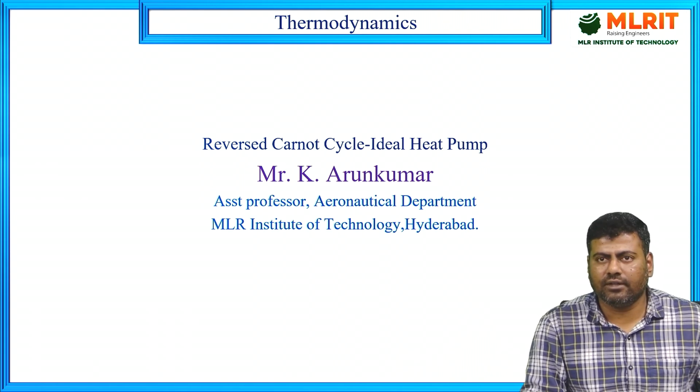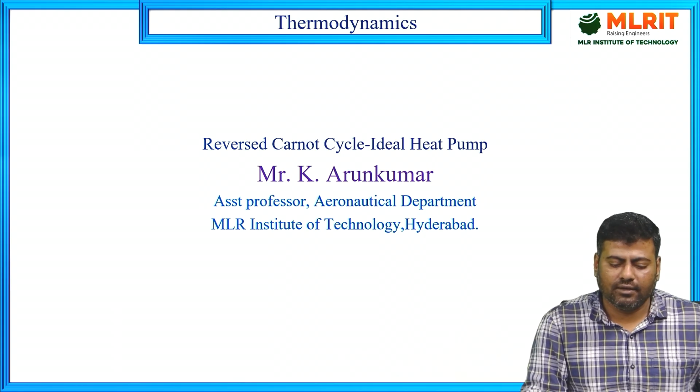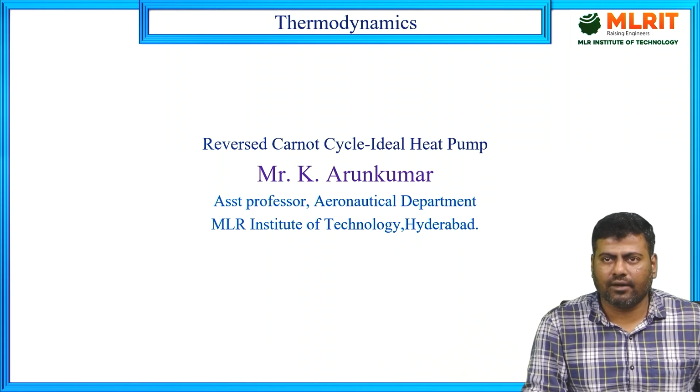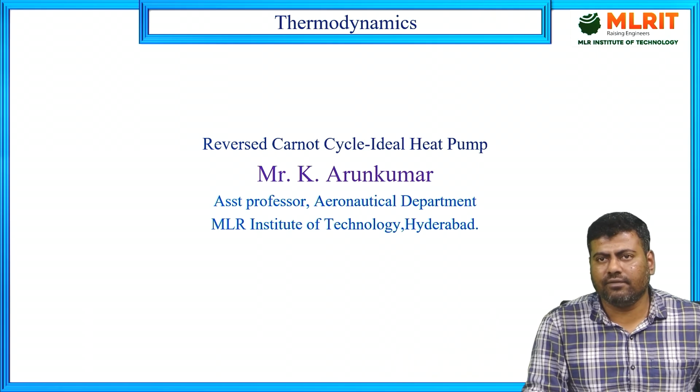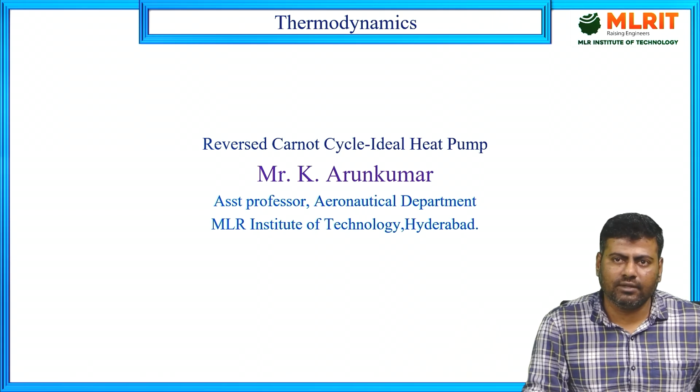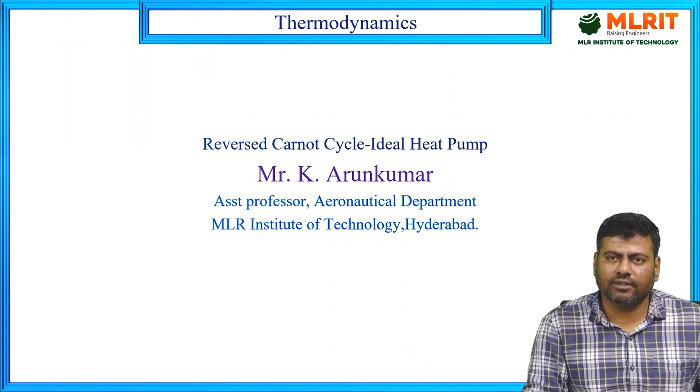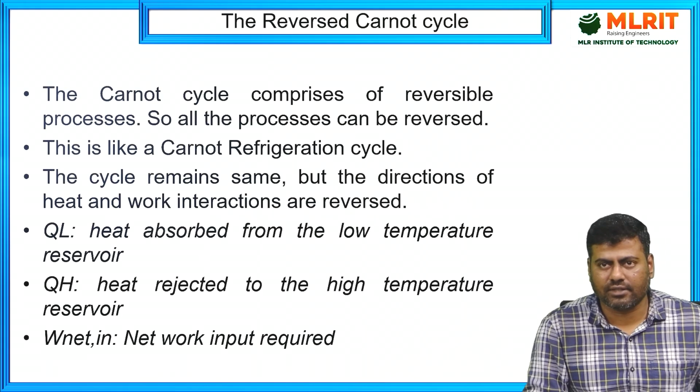In today's lecture, we are going to discuss the reversed Carnot cycle, or we can say the ideal heat pump or ideal refrigerator. In the previous lecture, we discussed the Carnot cycle in detail, which is applicable to the heat engine, with respect to the Kelvin statement. Now, with respect to the Clausius statement, we have the reversed Carnot cycle. The Carnot cycle which we assumed, we need to reverse the directions and assume the processes in the reverse way. Then we can frame the reversed Carnot cycle.